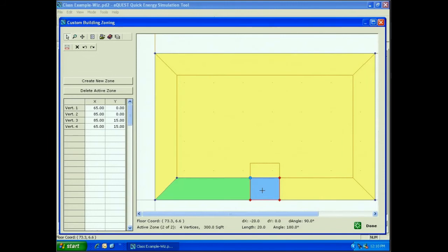Within your CAD file, you also want to make sure that your lines have endpoints where you want it to snap to. If you have two intersecting lines and there's no endpoint there, then within this screen, the vertex is not going to snap to that point. It'll only snap to endpoints on the lines, not intersections.